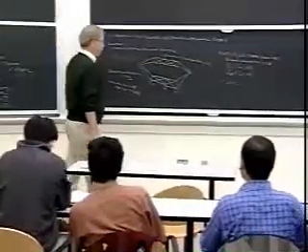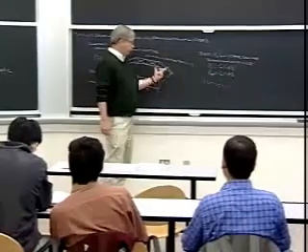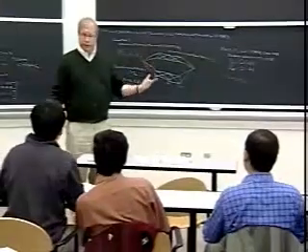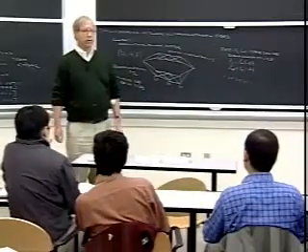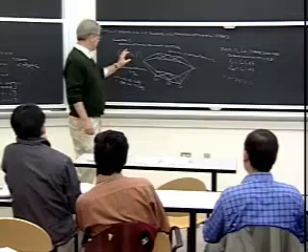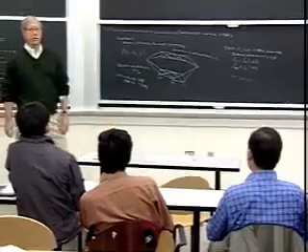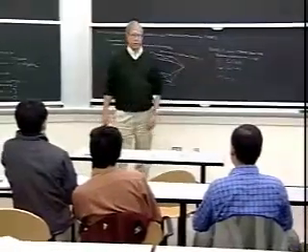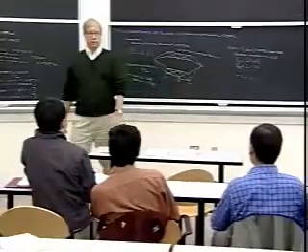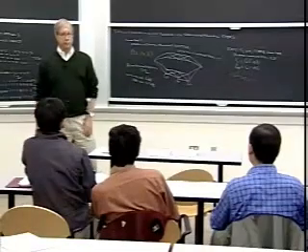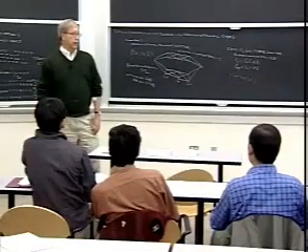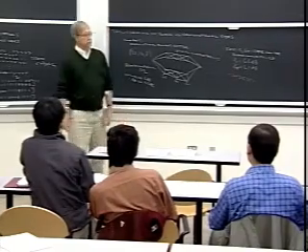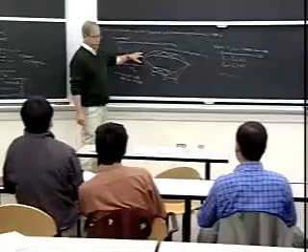If you needed the best possible performance and you were constrained in block length, you'd pick the best block code at the rate that you wanted, with the best minimum distance and the best effective coding gain, and you'd do maximum likelihood decoding with trellis decoding. But that's not usually the situation in data communications. Usually you have a stream of data or a packet of length at least 1,000. And then it would certainly be better to use convolutional codes and trellis decoding, as long as we're in this class of techniques.